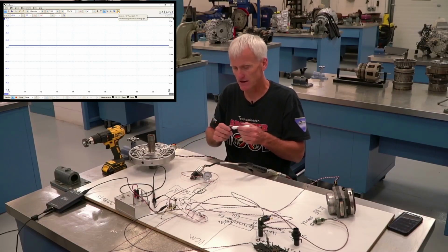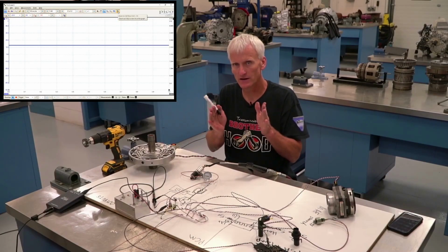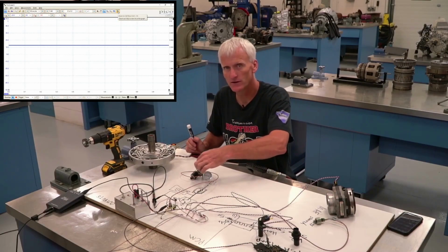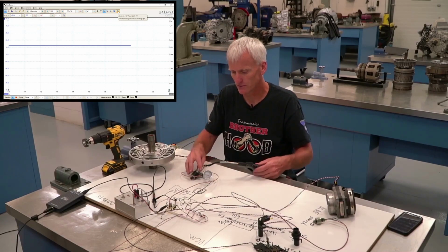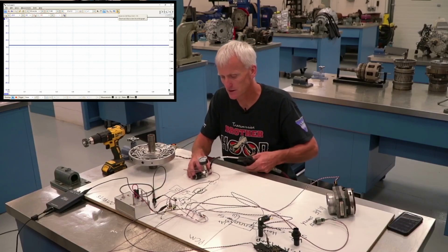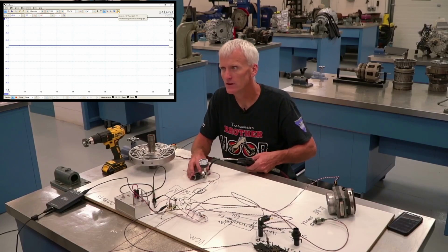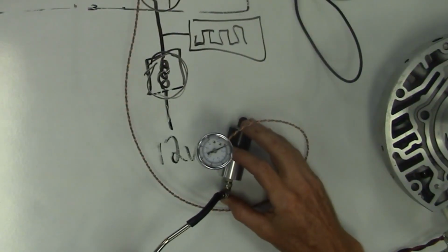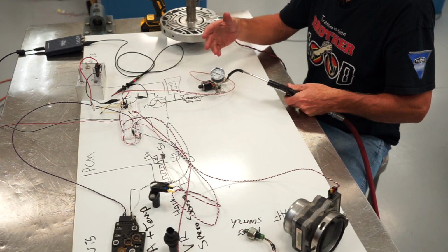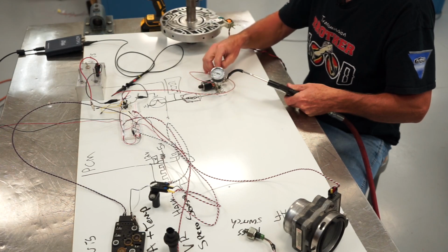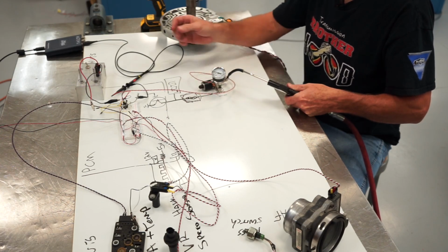The amount of time that they keep the pulse on is going to determine the position of the valve inside the solenoid, and it's going to ultimately control how much fluid pressure finds its way into the clutch circuit. So like right now with it off, you can see nothing gets trapped in there. You look at that gauge. When there's no electrical current flowing through it, it lets everything leak out.